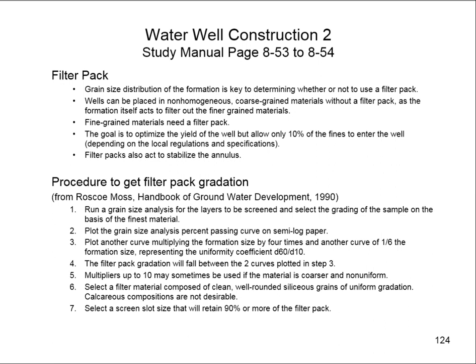And then you're going to go to the filter pack store and choose a gradation that falls in between those two parameters, those two curves that you've generated. You want to make sure that you're using siliceous grains and they're well-rounded, they're not calcareous. And you want uniform gradation of those siliceous grains. You're not going to have to do this for the exam, but I just wanted to put that in there as a way to get that filter pack gradation.